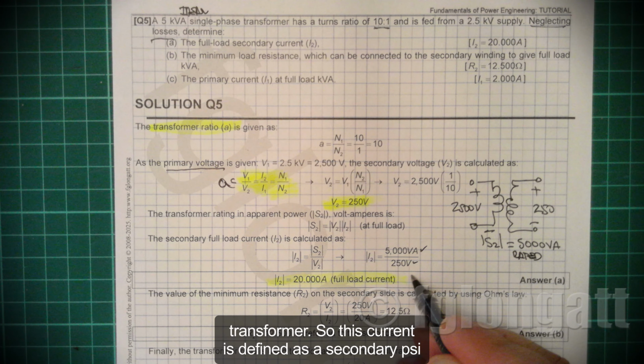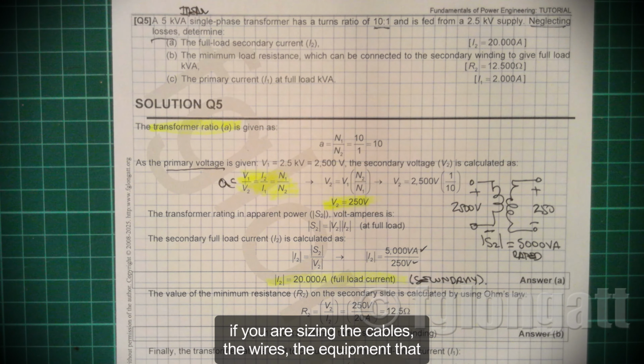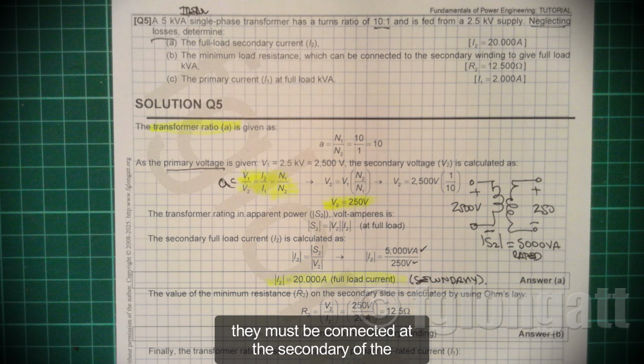This current is extremely important because if you are sizing the cables, the wires, the equipment that must be connected at the secondary of this transformer, you will be using these 20 amps as the main indicator to specify the cross-section area of the cable used in this problem, okay?